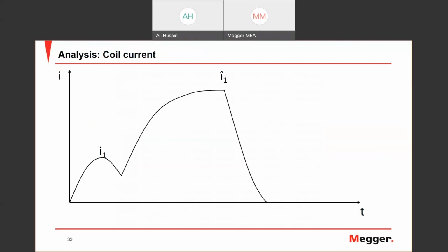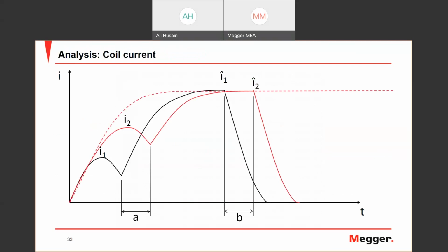And this is an example of a comparison between coil currents. This is the reference one and a first trip one, and you can see there are some differences in timings. Here, the mechanism time, the second jump, the higher jump, is very similar from the first trip to the reference, but the armature time, the coil time itself, has a huge difference between them.